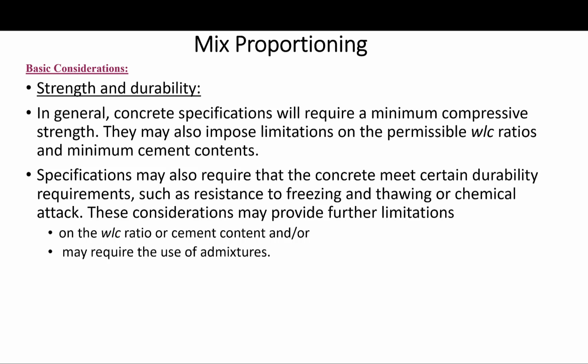Specifications may also require that concrete meet certain durability requirements, such as resistance to freezing and thawing or chemical attack. These considerations may provide further limitations on the water-cement ratio or the cement content, and in addition may require the use of admixtures. So many things to consider here.